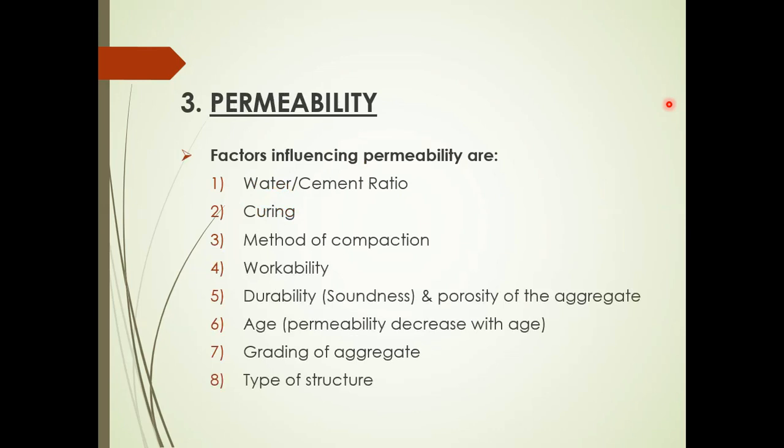Some factors that influence the permeability of the concrete are, first, the water-cement ratio, the curing process, the compaction, the workability of the fresh concrete, the durability, and also the porosity of the aggregate, the age, the grading of the aggregate, and also the type of structure that we are going to construct.